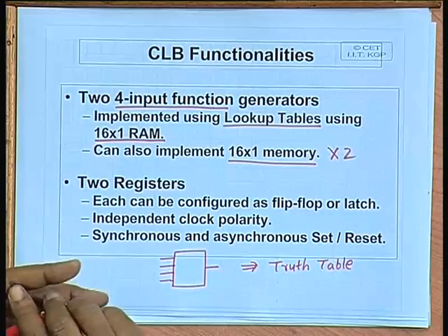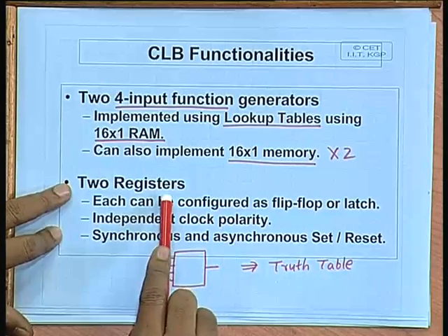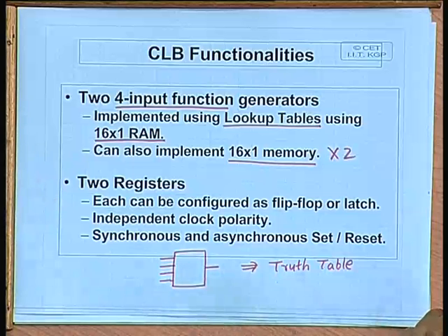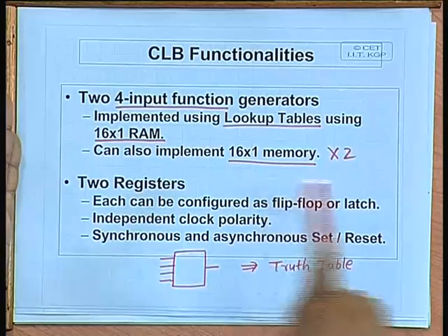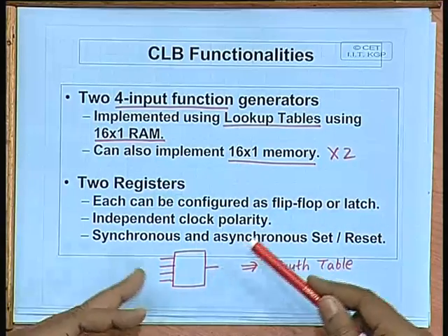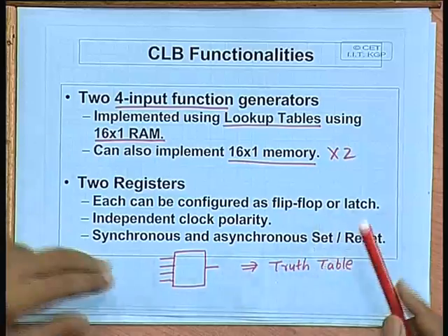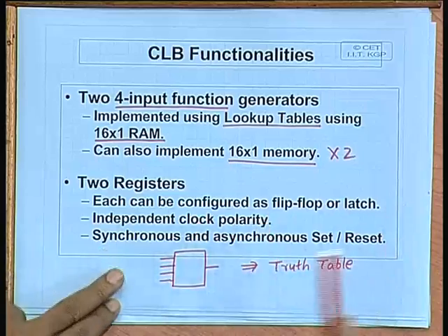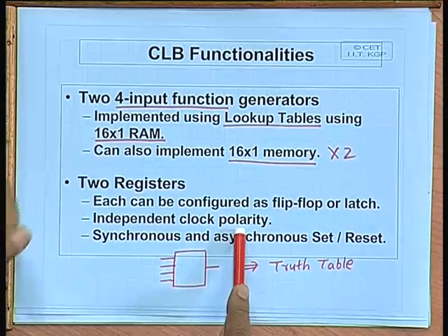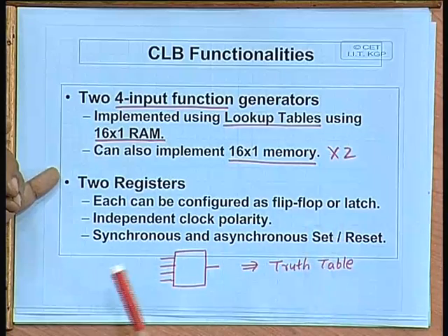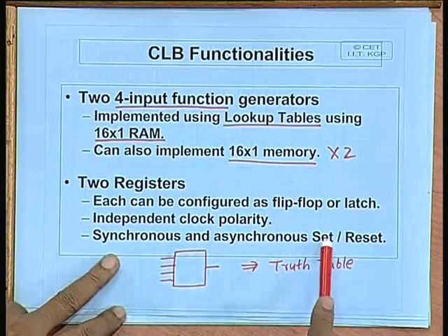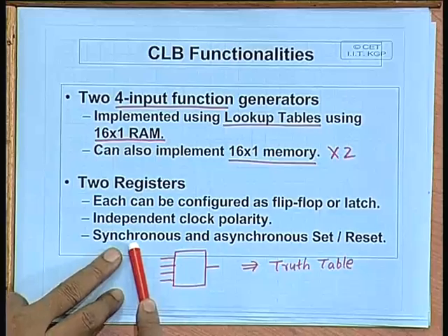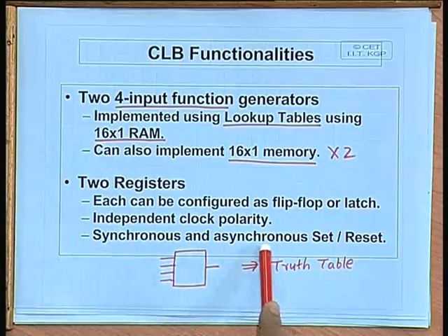And inside the CLB there are also 2 flip-flops using which you can also realize some sequential logic. There is some combinational part, there are also some flip-flops at the output of it. You can basically partition and design in a suitable way, so that you can have some sequential logic also. And they are also fully programmable, you can have it leading edge or falling edge triggered, you can have it in the latch mode also, level triggered. Set reset can be synchronous with the clock or it can be asynchronous also. So, it has complete flexibility, you can have anything you want.